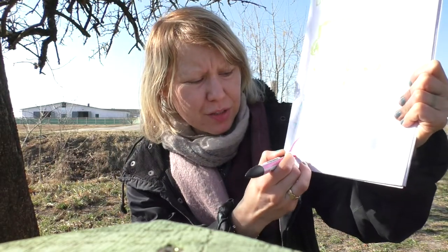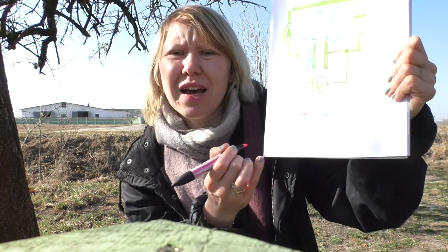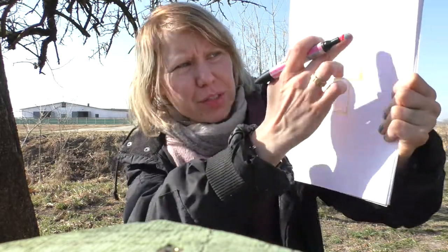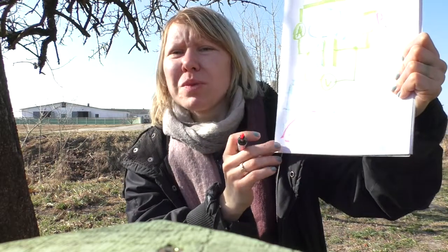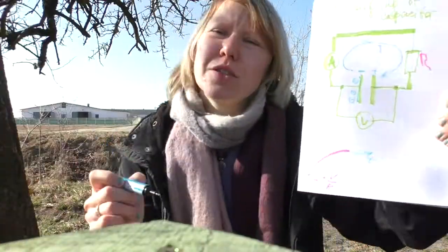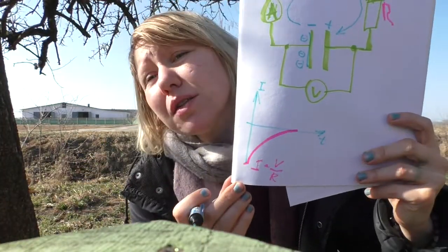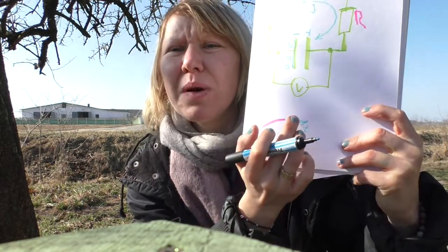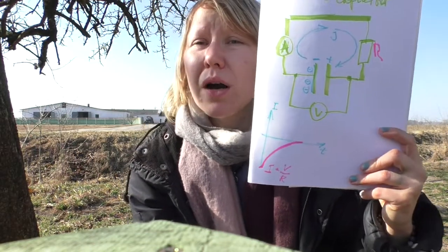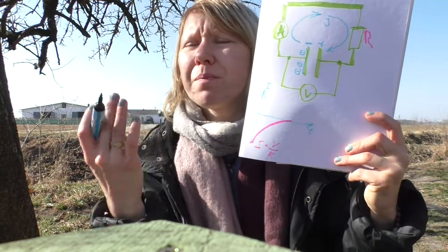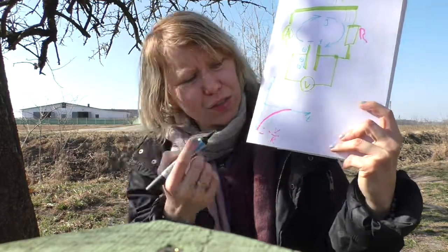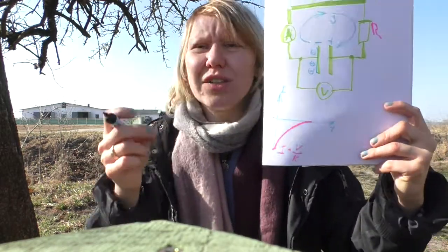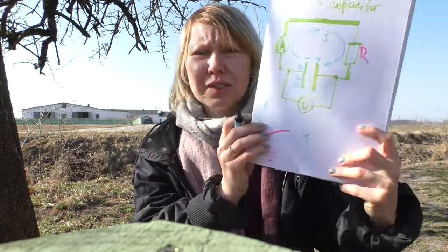And here will be the initial current. The initial current is the voltage collected on the capacitor divided by resistance. Our resistance, this one. So it's Ohm's law. Yes, very popular Ohm's law. Okay. And we can notice that the current is painted not from the top, but from the bottom to the top. It means we draw it like that because our current changed its direction. So we can draw it like the current has a negative direction now. So this minus means only changing the direction of current. The amount of current is the same.